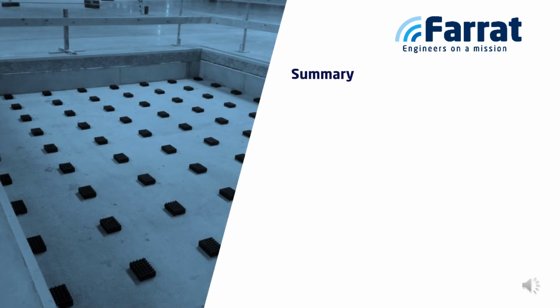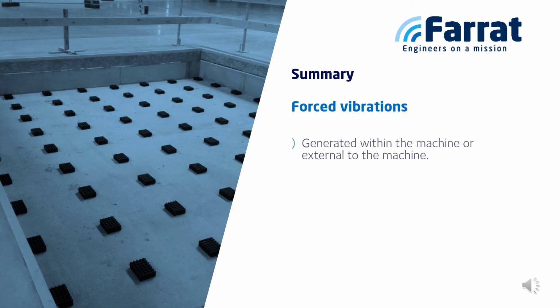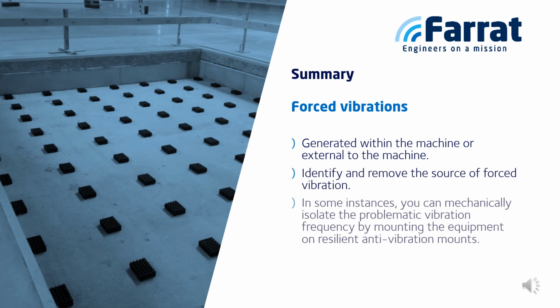Now that we have explored each type of vibration, their impact, and how the effects can be resolved, let's summarize our learnings. Force vibrations can be generated both within and external to the machine. To combat force vibrations, remove the source of the vibration. In some circumstances, you may need to mechanically isolate the problematic vibration frequency by mounting the equipment on resilient anti-vibration mounts.